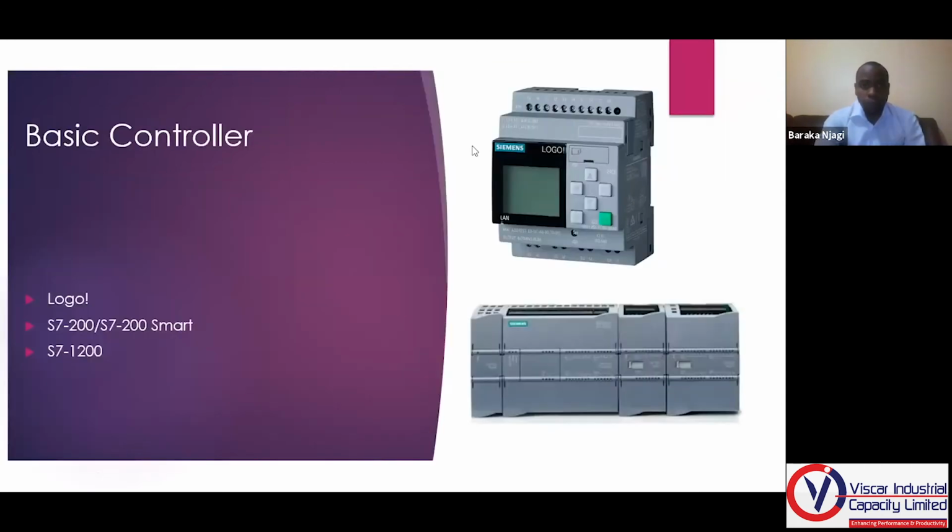This is your basic controller, and I have given you examples. I am sure you have seen all this somewhere. If you have not seen, at least you can see. So we have the basic, which is a LOGO, Siemens LOGO, and it usually has 8 inputs and 4 outputs. It can be programmed using the screen that you can see right there, or using a programming cable connected to it. We also have an S7-200 and an S7-200 Smart.